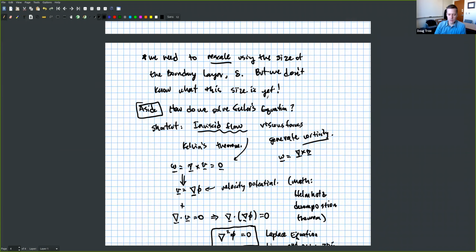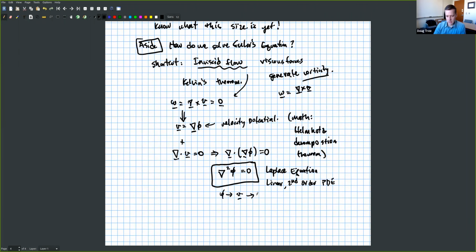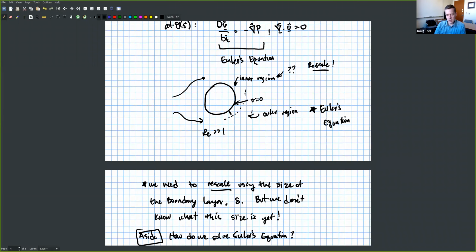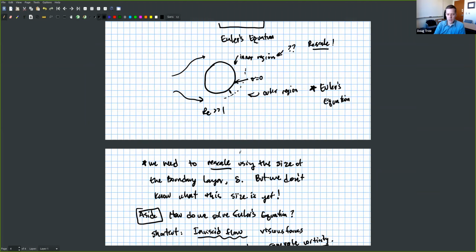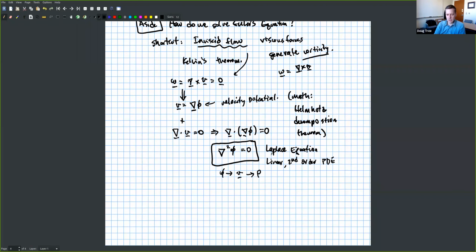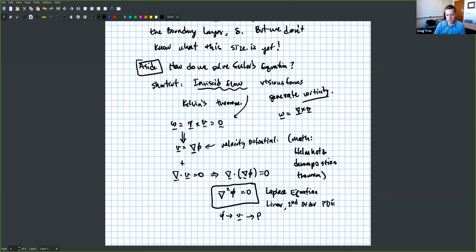Okay, so you can use that to get the pressures, so long as you're in inviscid flow. And that's almost always the case, because if you're saying an airplane, you might think, well, how is that inviscid? I've got these big wakes and whatever, but it turns out the wakes are in the inner region. And so you only care about the outer region, and you can solve this Laplace equation using the shape of the wing. And we'll see in a second how that's going to couple to our boundary layer problem.